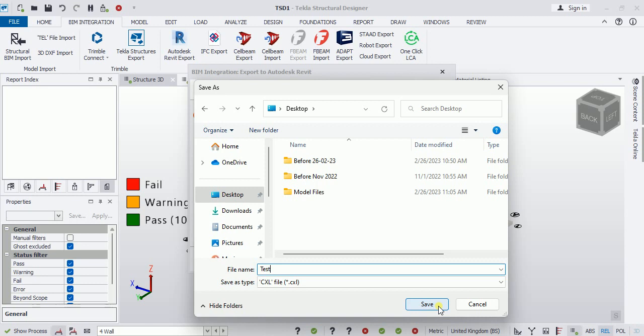The program has different types of analysis, even for static and dynamic. Okay. You have, for example, pushover. You have spectrum. So it depends on what level of detail you want. Automatically he will understand. If you are not doing wind and earthquake, you will not go for second order and complicated analysis.